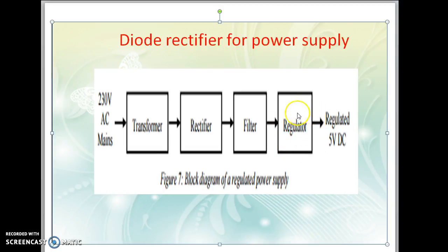A regulator is a circuit which maintains the output voltage or current in spite of changes in the input voltage or load variations. So we use a regulator circuit to provide voltage regulation. A number of regulator circuits are there. The regulator is made from transistors. However, some ICs are available in the market like 7805 in order to get a 5 volt regulated output, and 7905 for getting a -5 volt regulated output voltage.